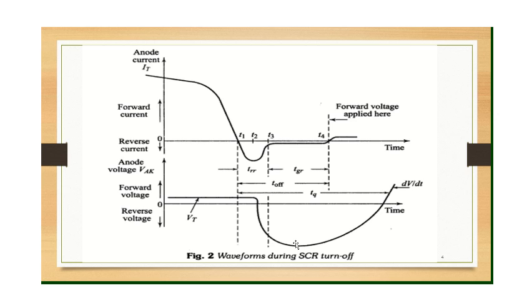Now, the total reverse recovery charge for the duration tq, how much time is it taking for the total recovery? It actually depends on the magnitude of the forward current. Obviously, the more the magnitude of the forward current, the more charge carriers would be available in the device.